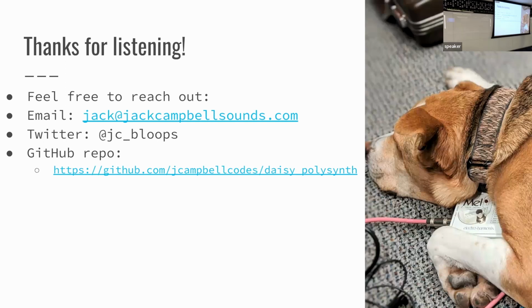Yeah, I don't know, but worth a try. Embedded folks tend to be really cautious about any sort of dynamic memory. I don't know if coroutines use it. They do require it. A lot of embedded systems are really hesitant about dynamic memory because it leads to memory fragmentation, especially when it's supposed to run for a long time. So I think people would tend to shy away from it.